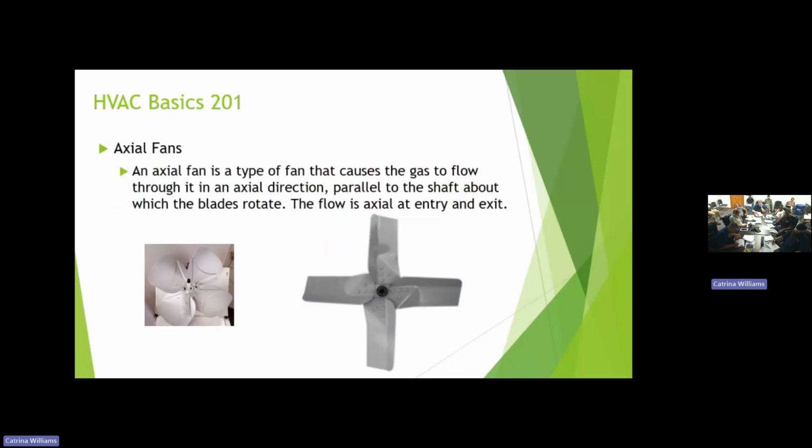So again, the typical fans that we use in Dallas are centrifugal, and there are 3 variations of centrifugal or axial. Axial fans, we said before, they move a lot of air, but they can't handle static. So once you start getting any static in the system, you very seldom see these working because of the limitations.